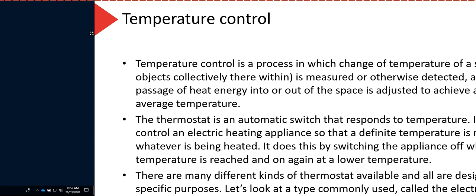So usually you'll have hysteresis, which is the variation between the on and off time. So if I set it to 24, it's probably actually going to switch off at like 26 degrees and switch back on at 22 degrees. It'll be plus or minus 2 degrees, something like that. So then I'm not even going to get 24. All I can say is, well, it's probably somewhere between 22 and 26.